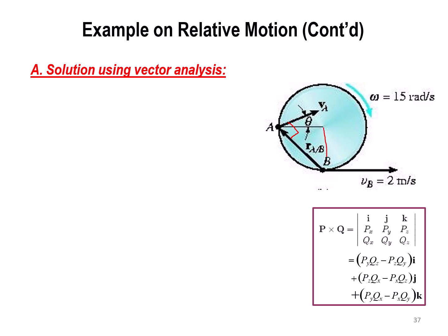Now if I sketch here, this will be 0.5 meters because this is the radius, and this is another 0.5 meters, so I can find the length AB directly, which is the square root of 0.5 squared plus 0.5 squared. When I find r_AB, I know omega, and then I can simply find the velocity at the point A. By finding the velocity at A, I can find the velocity at B. It's not going to be only 2 meters per second, but it's going to have two velocities, and we can find that using the relative velocity equation.